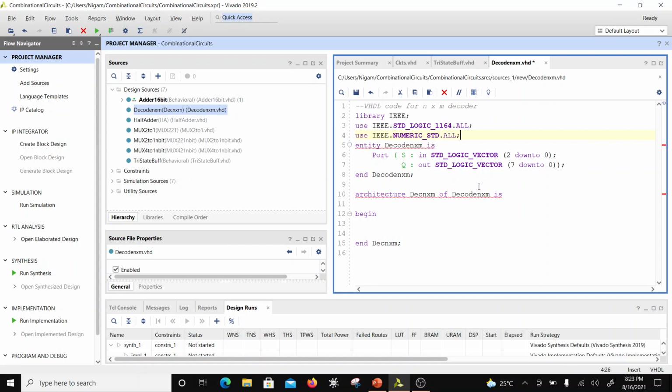Okay, this will allow me to convert a std logic vector into an integer directly, and internally it is optimized because it is implementing something called b merge, rtl_b_merge. So this is a special RTL component which is created for this purpose. So it's not going to have a converter to convert a std logic vector into an integer. Internally there is something called b merge, and you can read about this in the manual. Okay, so let's do that.